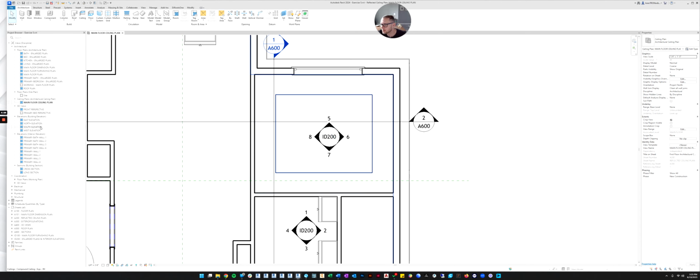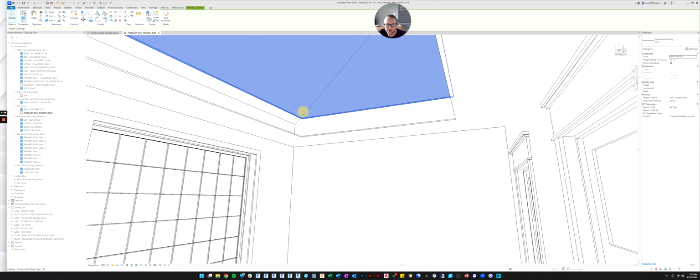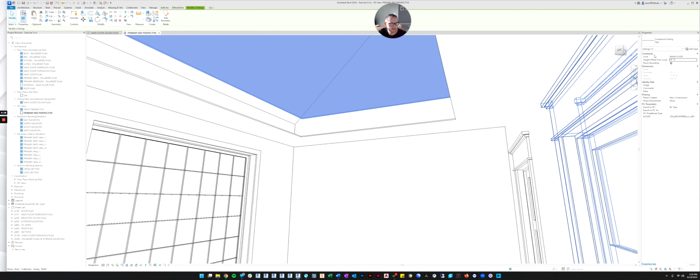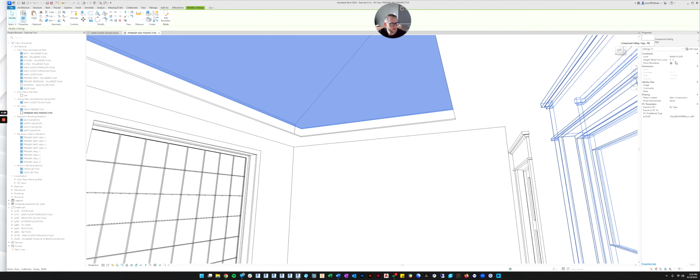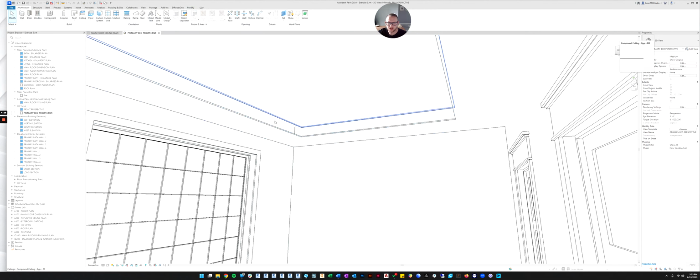Let's look at our 3D view, primary bed perspective. Oh, you can see that it made it, so that's good. Maybe 9 feet or 10 feet is too high. Let's make it 9.5 feet. So I'm going to select the ceiling, go over here to its properties, and change it to 9.5 feet off the ground. So now we've got a little bit of a pop-up in our ceiling.